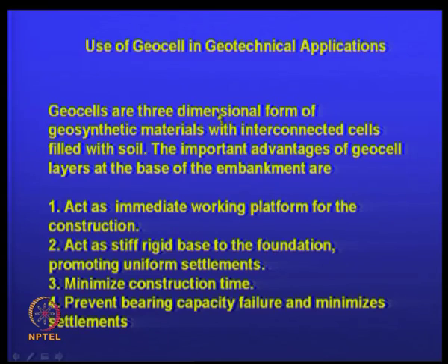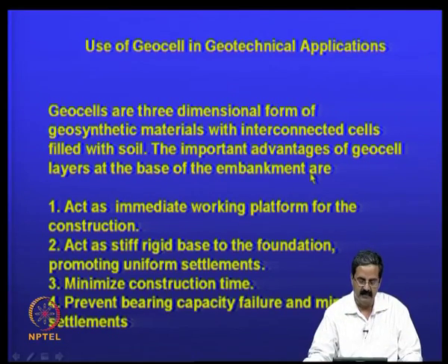In this lecture on design of embankments on soft soil using geosynthetics, we would be seeing the use of geocells. The geocells are a three-dimensional form of geosynthetic materials with interconnected cells filled with soil. It can be stone, or even it can be a marginal material like fly ash. The important advantage of the geocell layers at the base of the embankment is that it acts as an immediate working platform